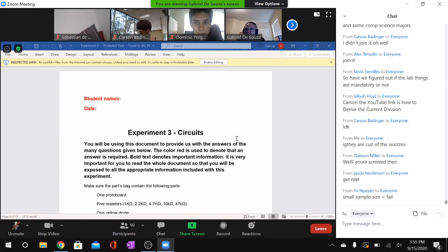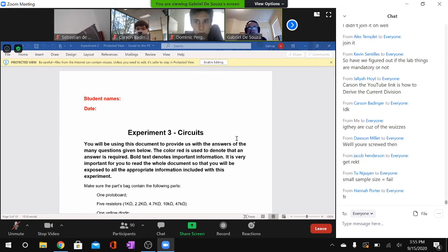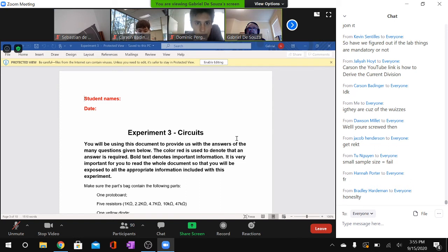But the important thing, why am I asking you to do that? For you to learn how to measure a voltage. That is the whole purpose. After you learn that, the measurements will become second nature for all of you. One thing that you have to realize is that every voltage measurement that you make is across a device, from one side of the device to the other.